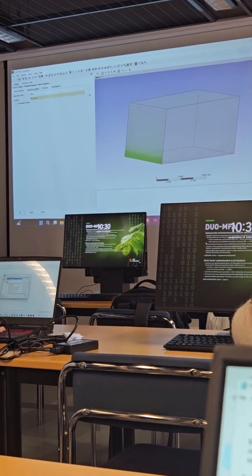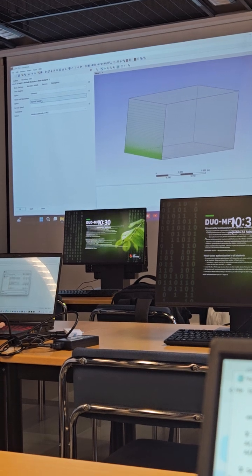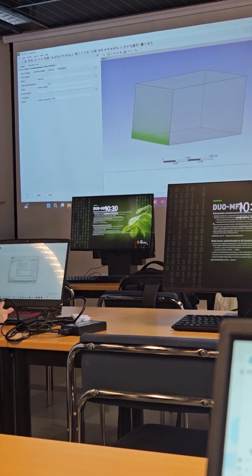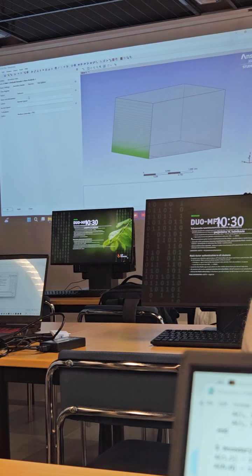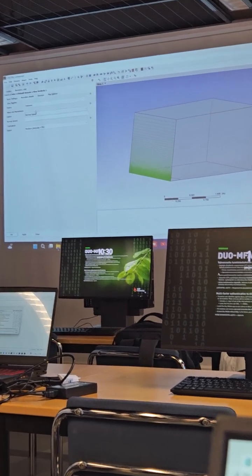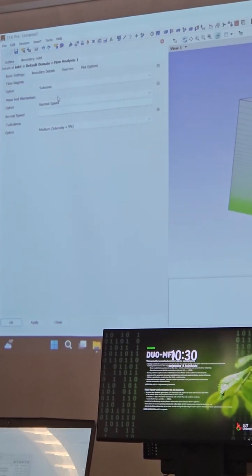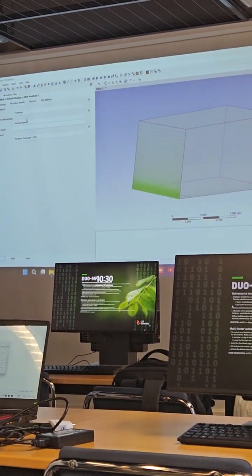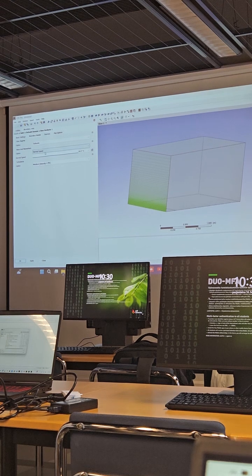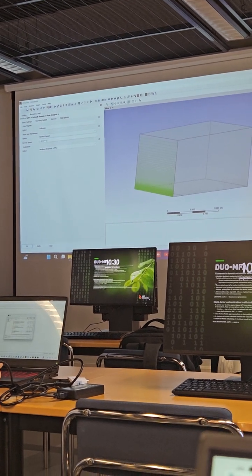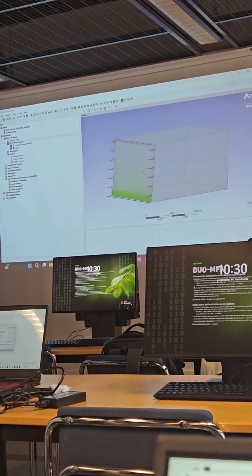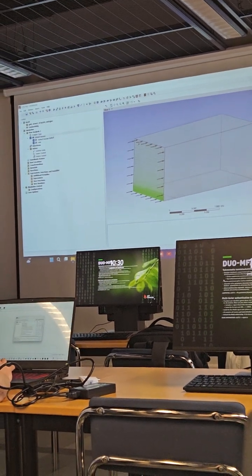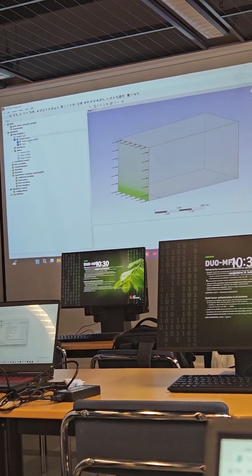Then you can also set some boundary details. In Fluent, we should set total pressure and total temperature. In CFX, we don't need to set that already because that information will be lost when we upload the case in Fluent. So we can just put one dummy value here. It doesn't really matter. We are just setting the inlet boundary condition there.